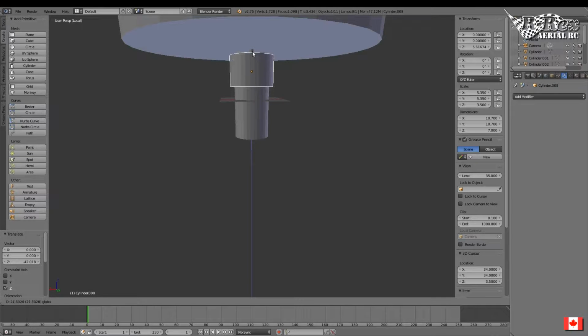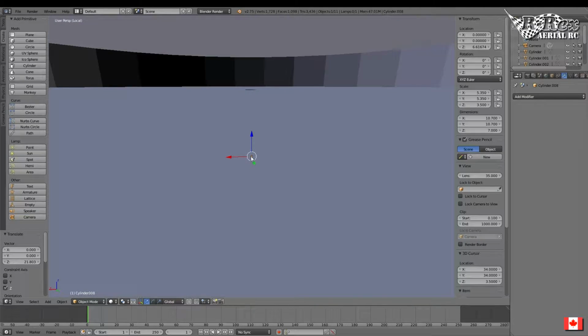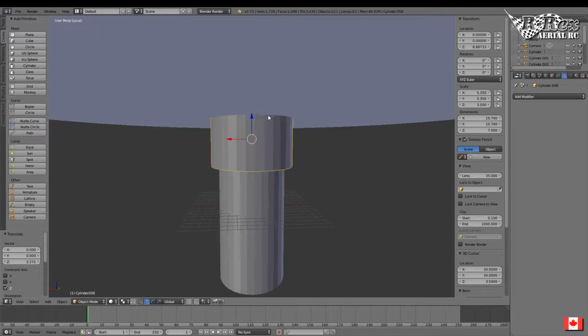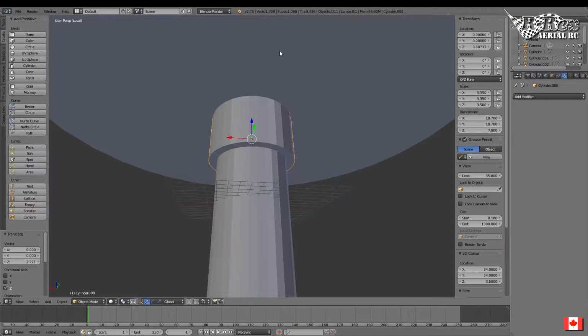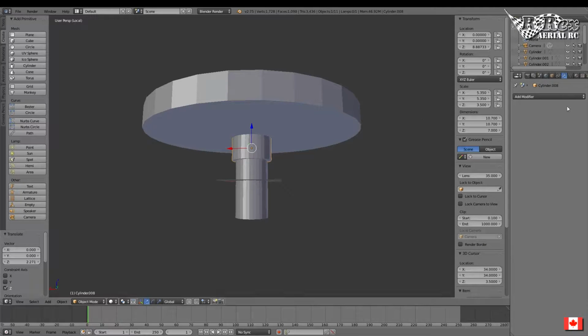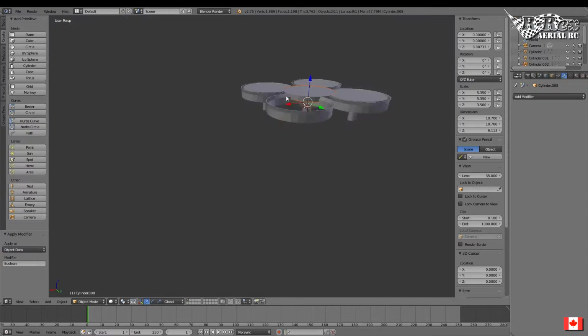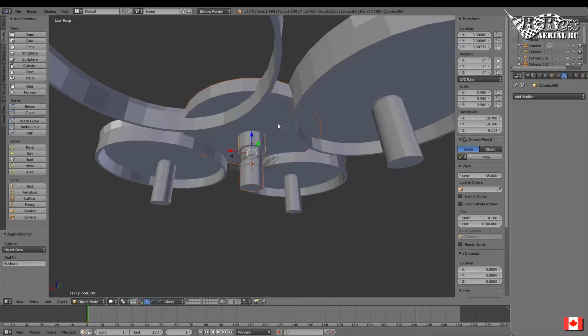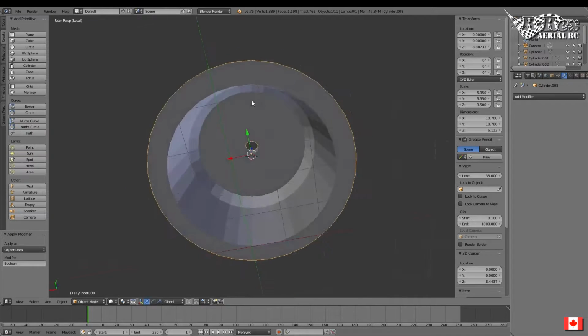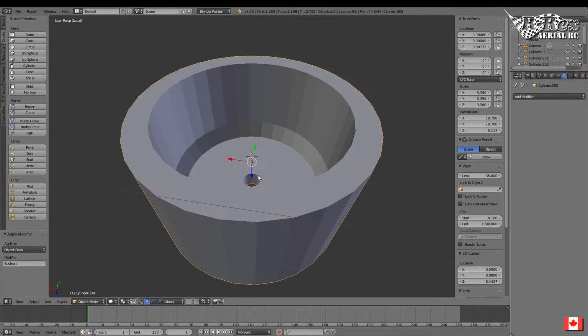Okay, so we slide this right on up our motor. In fact, actually, you know what? For ease, I'm going to slide it straight on up into the top of the other one. It's going to give us a clean cut. The measurements are going to be good. So I'm going to go over and select Boolean difference. Done. Apply. Let's go back, center, select the object, isolate the object, and now when we look at the object, we have a closed-in motor face.